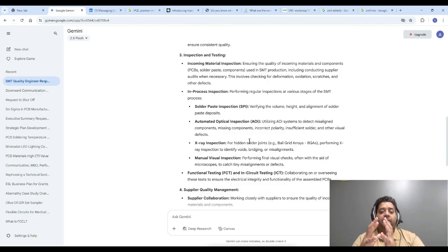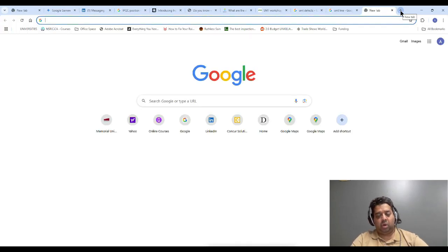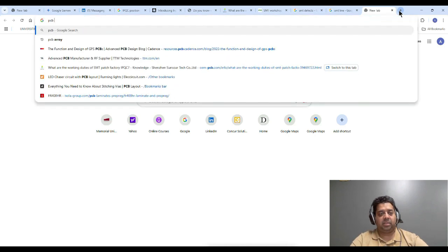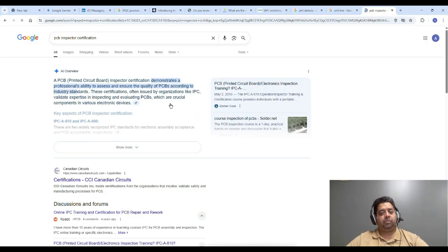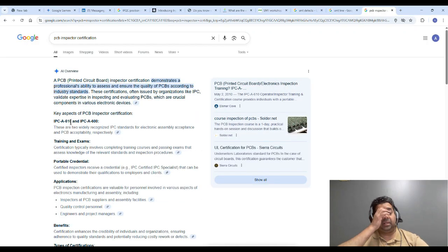And your visual inspectors should be IPC certified. Now, what does IPC certification mean? In Toronto, we have a company that does the training for PCB inspectors, and then they certify them. Let's say PCB inspector certification. Your inspectors need to be certified for IPC 610 and IPC 600. 600 is the PCB level, 610 is the PCBA assembly level.